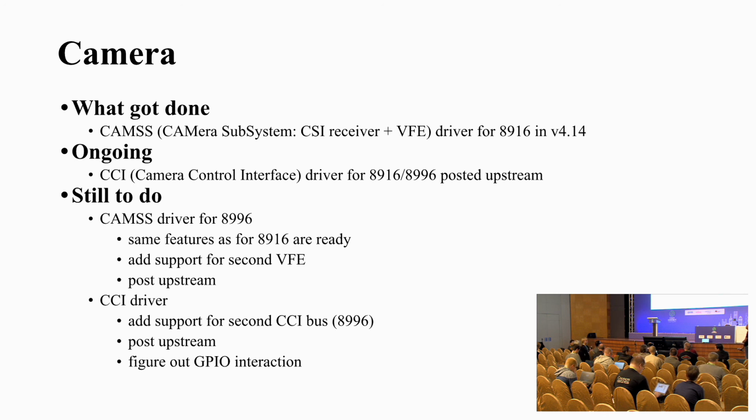There are even more functionalities in the CCI, because you can synchronize the CCI commands and the GPIO with the frame start and end. Right, you can wait. So it goes a lot beyond the I2C driver. But this is something new, and I don't know how we can handle it. Wolfram didn't show up for some reason. Maybe we can attack Linus.